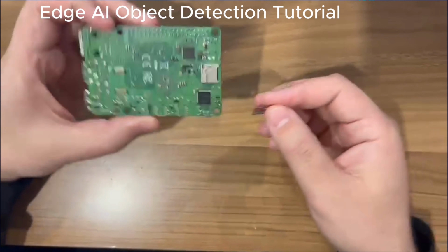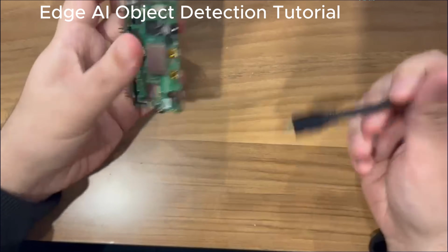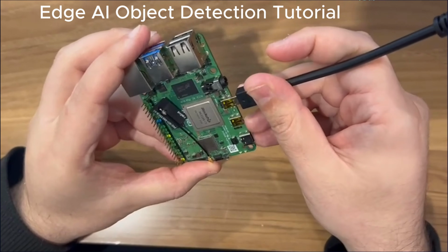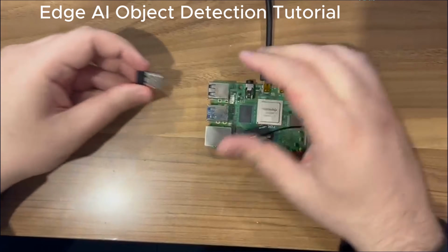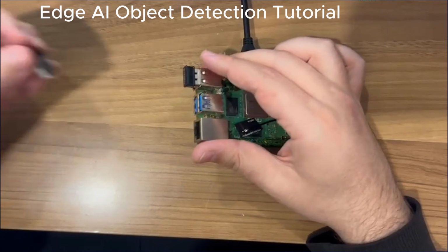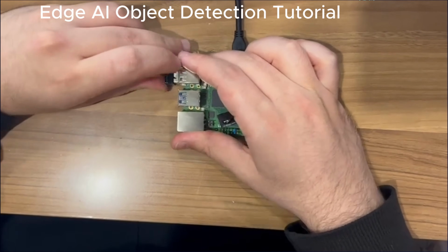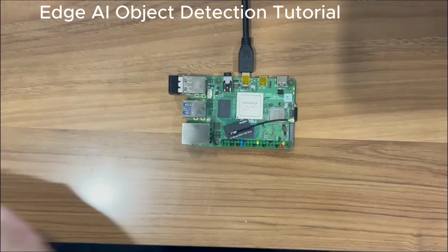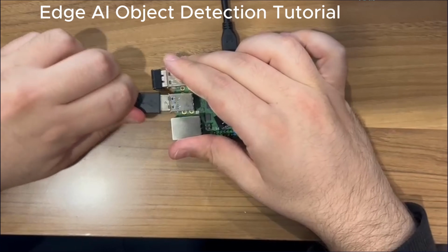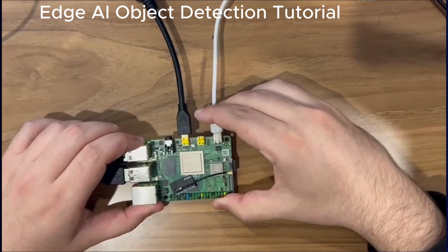I then took the microSD from the reader and inserted it into the back of the board, followed by connecting the micro HDMI to the micro HDMI connector. This will be used later on to connect to the monitor. Then I connected the USB connectors for the keyboard and the mouse, followed by connecting the USB camera. The final step was to connect the USB-C for the power.